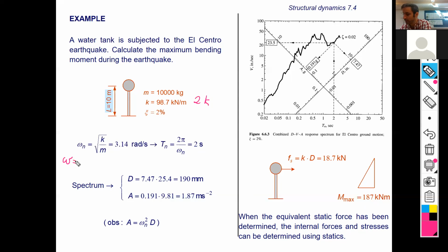So the new frequency is going to involve the square root of 2, right? Now we have a 2 in the square root. So the frequency is going to be the square root of 2 times what it was before, which is 1.7 something, the old stiffness. It is 1.7, right? Yeah, I think so. And so now the period is going to be slightly lower. I'm guessing here, I don't have a calculator, but if it was 2 seconds, maybe it's going to be 1.3 seconds, let's say. That's the new period.